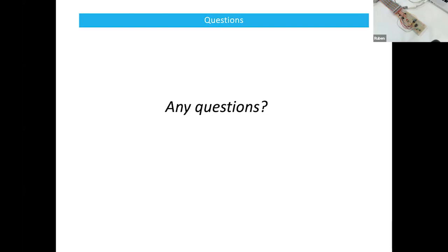Then, because my first core has already grabbed those GPIO registers and set a spin lock, the other CPU core sees that and then just spins on itself. It's just waiting there. Spinning clock cycles, essentially. That's where the spinning comes from. And then when my first CPU core has finished, either the driver is finished using those GPIO registers or something else is finished using them, then that spin lock is released, and that second CPU core will grab the lock and then stop any other core accessing those registers.